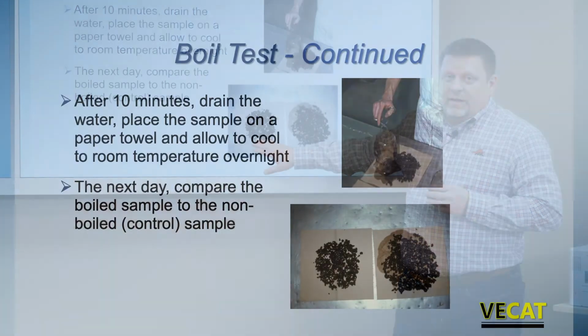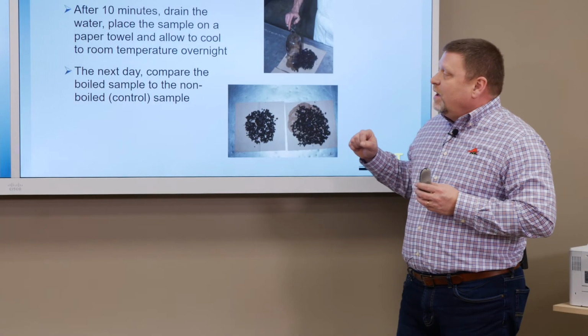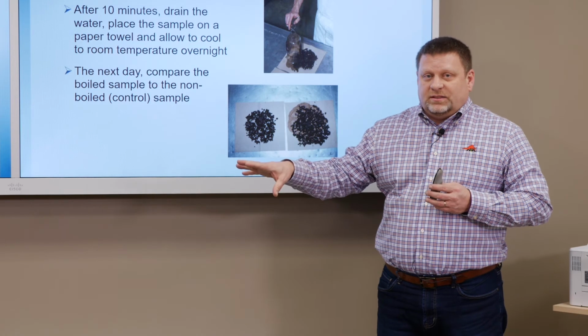Now, the reason the boil test went away is it doesn't give me a passing number like the TSR does of you got to be 80 or better to meet specification. So it's not a defined number. It becomes a visual inspection, which does put a bit of opinionated variable into this test. But what it's telling me now, I know that my TSR is passed.